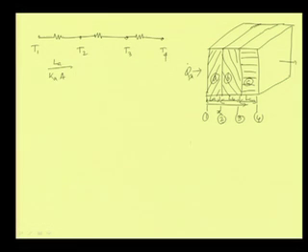If you see, the area for all the cases is common. So, I will say R1 is equal to this, R2 is equal to L_B by K_B into A, and R3 is equal to L_C by K_C into A, where K_A, K_B, K_C are the thermal conductivities, and A is common for all the cases. Now, at steady state,